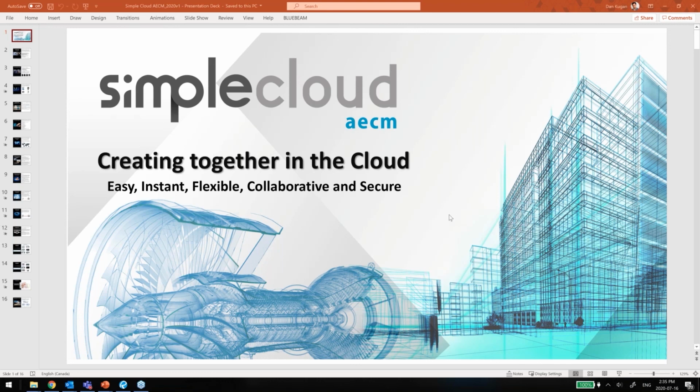Great. The other question: would this integrate with the central file in the office? If you're using Revit, you could technically set up your Revit file in the cloud infrastructure, or you can have a remote desktop or VPN tunnel into your hybrid server, or even better, use BIM 360 Design, which would be the simplest way to collaborate between your virtual and office environment, as well as your external consultants.